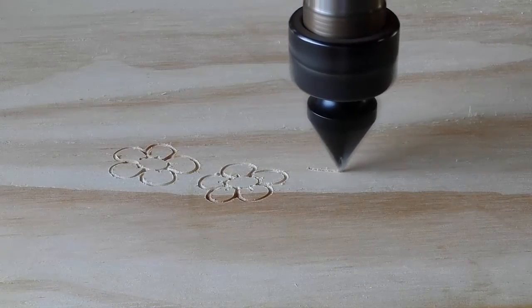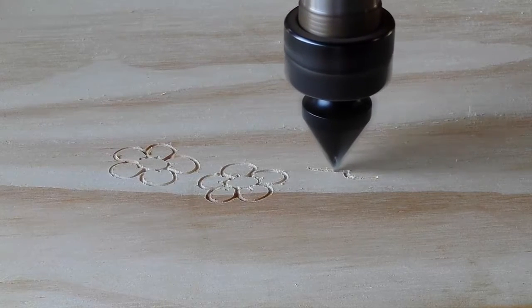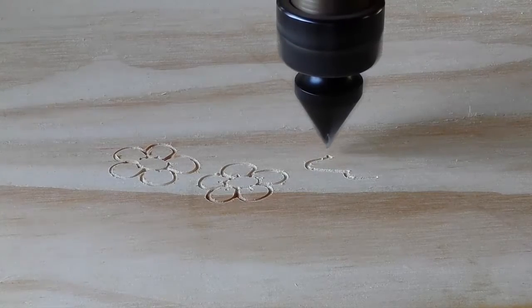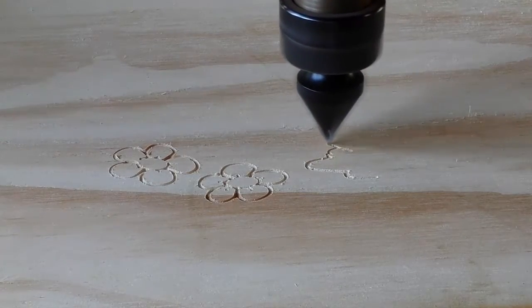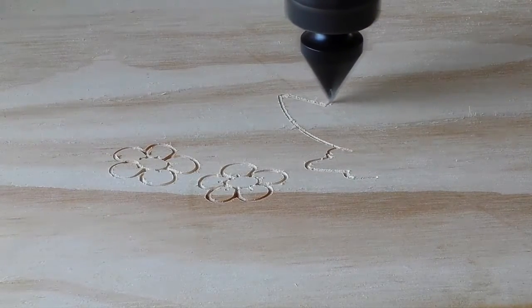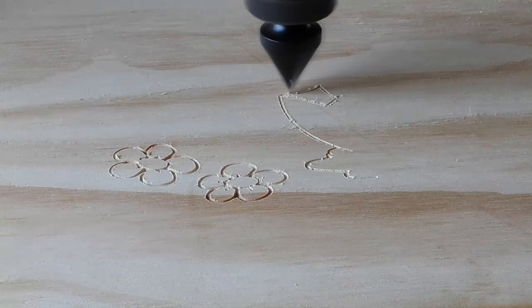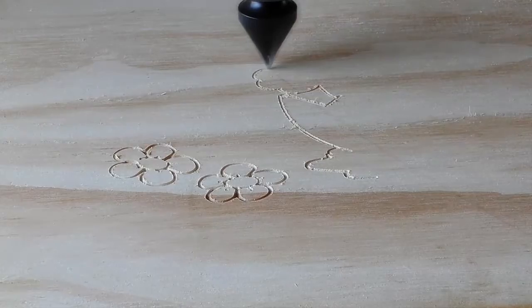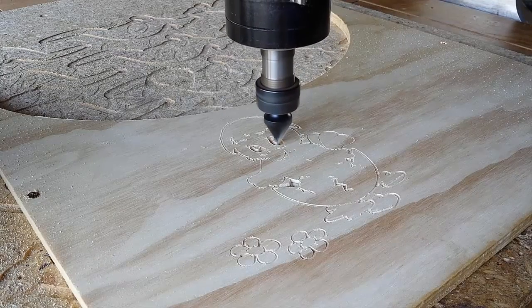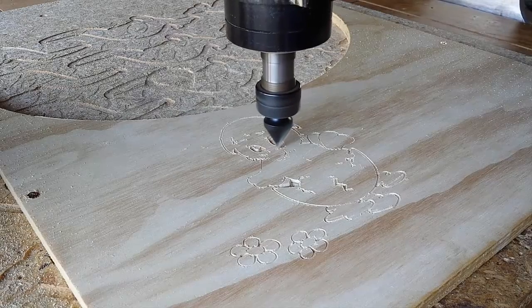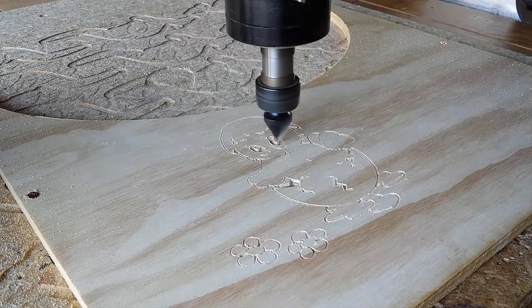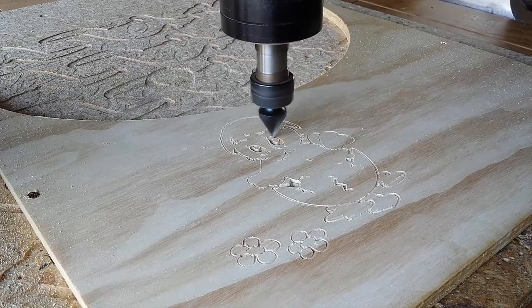As much as I like watching the CNC router do its job, for this task it soon becomes painfully obvious that the machine is running way too slow. Before the job is finished, I throw in the towel and start again, with a much faster feed rate for the router. Also, I decided to make the job about 25% smaller, just to see what effect it would have on the depth of cut with this set of vectors.